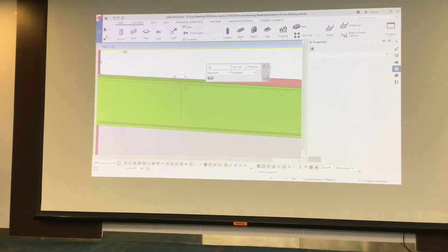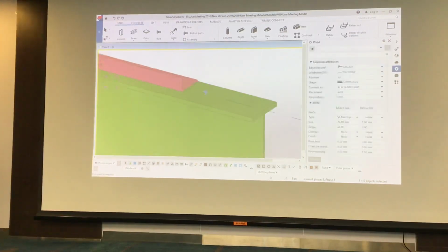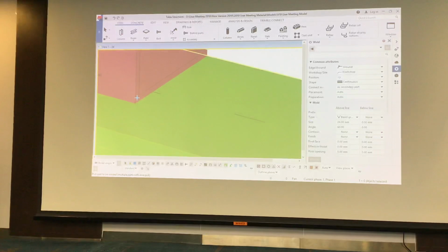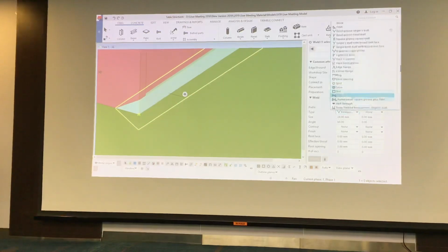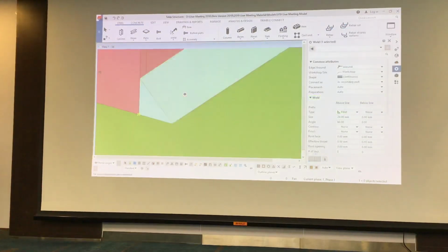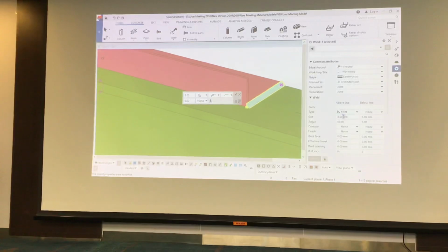Okay, a couple more little things. Let me just close that, move around here. Let me just draw some more welds on for you. So if I say weld, polygon weld, let's say that one to that one, and it welds from here to here. So that's my first weld. I'll click on that and say that should just be a fillet weld. And let's say that should be size typical 8mm. Let's say 8mm weld. That is ridiculous. I'll make it something like 4mm.